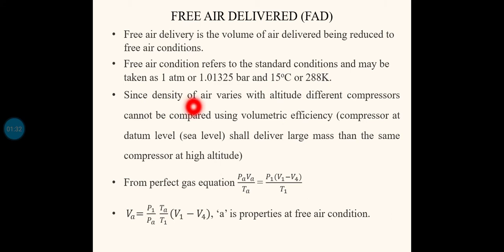Why are we choosing free air delivery? It is just for comparison purposes of the compressors. We have to compare the performance of the compressors, so there should be some measure for that. If the same compressor is operated at different levels, then its performance depends on how much air is actually sucked into the cylinder.